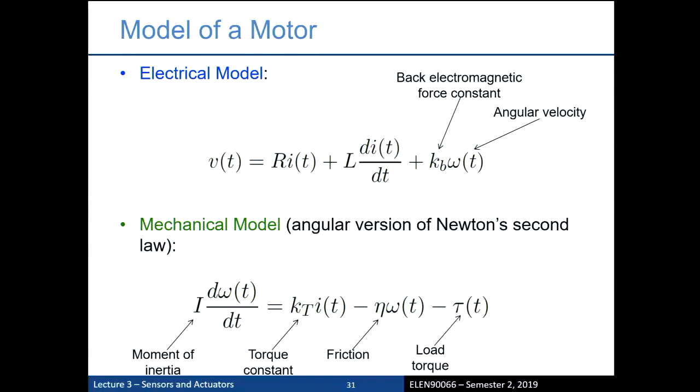There's coils inside them. Coiled wire means inductance. And it has a bit of linear resistance as well. So it's a first-order model in terms of the current there. But more interestingly, that last term is a term that generates a back EMF.